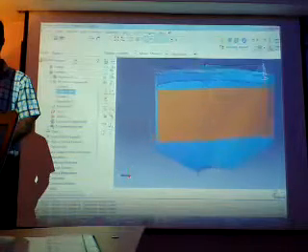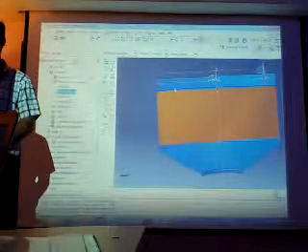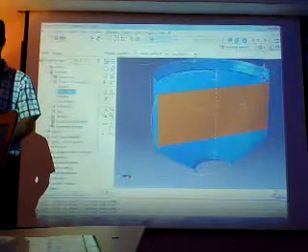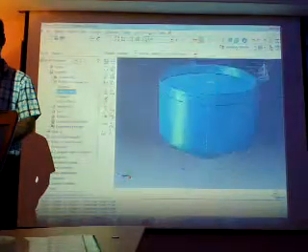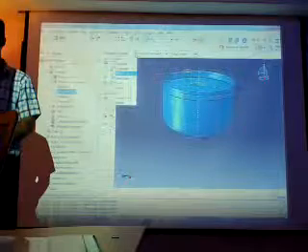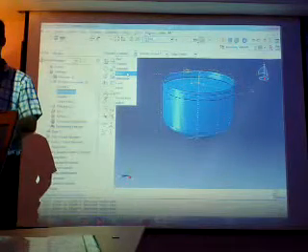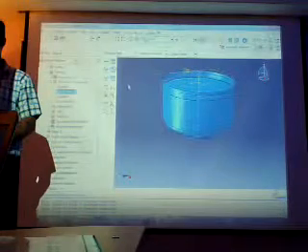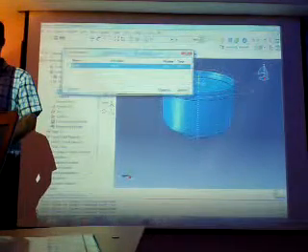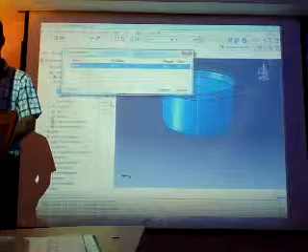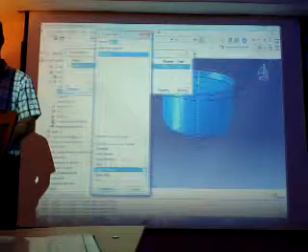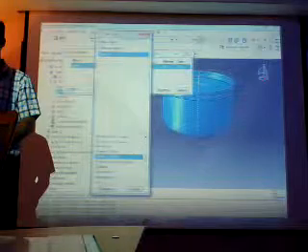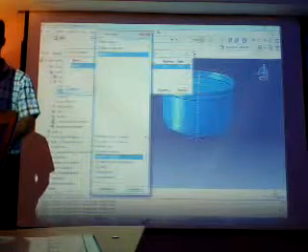You can see the upper section. This is the die, this is the billet, this is the punch. Next module is step. We have an initial step as default. Here it's important to take dynamic explicit. Okay, we'll just skip this step.